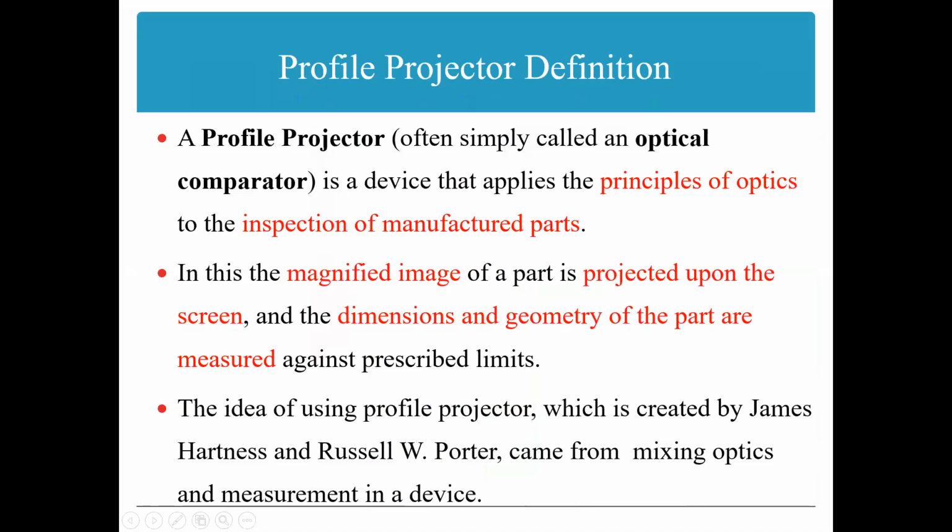Profile projector definition. A projector is a device that applies principles of optics to the inspection of manufactured parts. Principles of optics are utilized to magnify smaller size objects a number of times, in order to clearly visualize different features of the smaller object. The magnified image of the part is projected upon the screen, and the dimensions and the geometry of the part are measured against the prescribed limits.